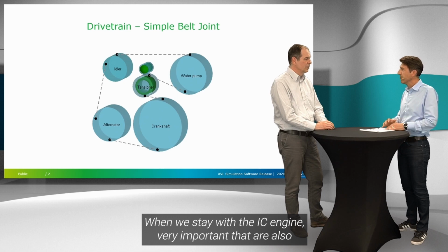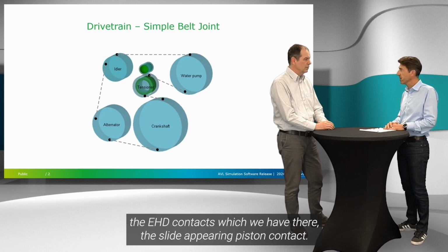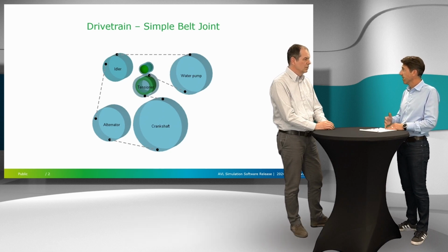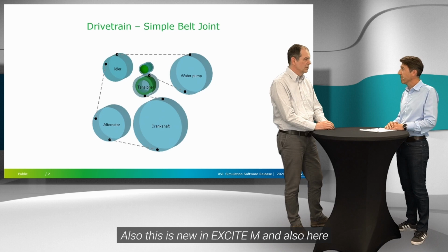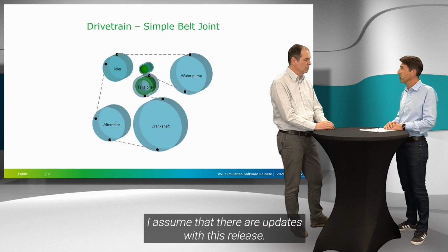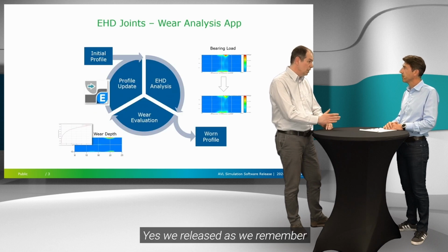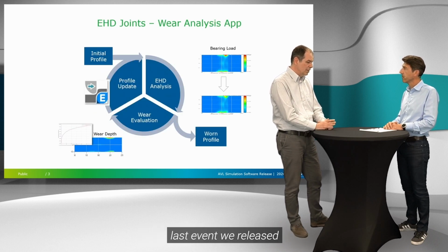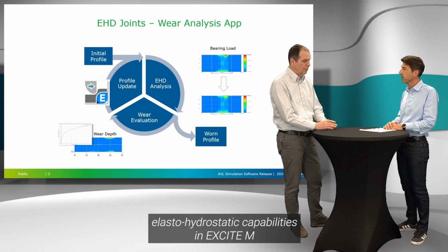Yeah, when we stay with the ICE engine, very important are also the EHD contacts, which we have there, the slider bearing, piston contact. Also, this is new in EXCITE M, and also here I assume that there are updates with this release. Yes, we released, as we remember, last event, elastohydrodynamic capabilities in EXCITE M.